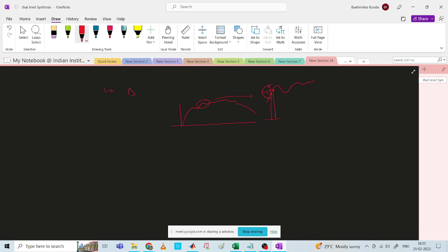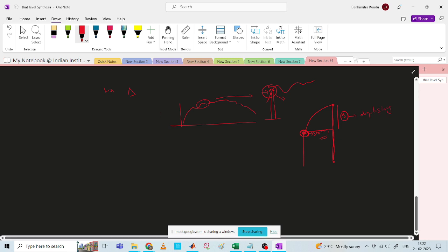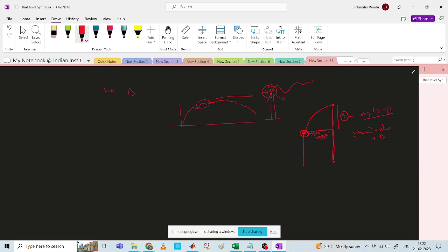If you zoom into this portion, you have coded this portion, right? Instead of sampling it and coding it again, you store this value. After you store this value, you check only this difference, del. After digitizing del, you store the digitized value of del with the stored value. Okay, sir, this process is an iterative process?